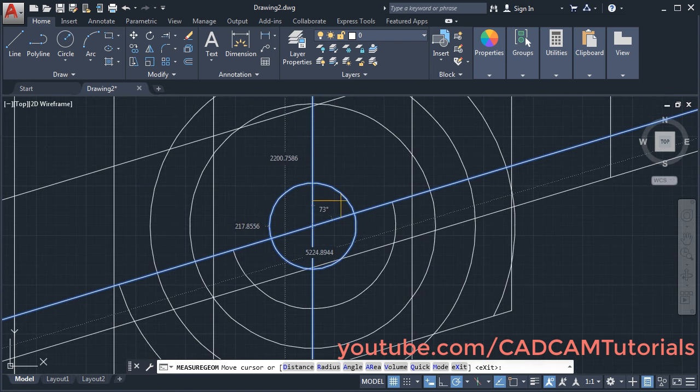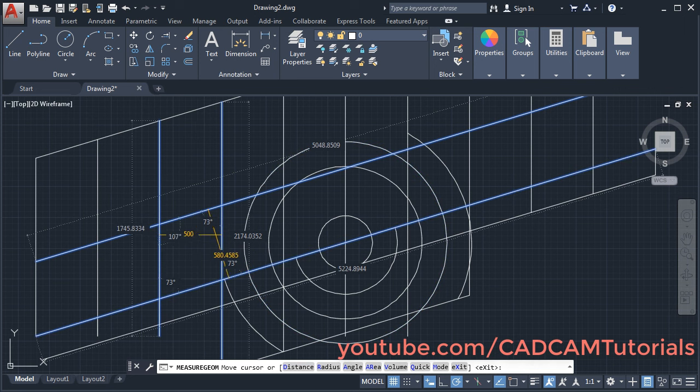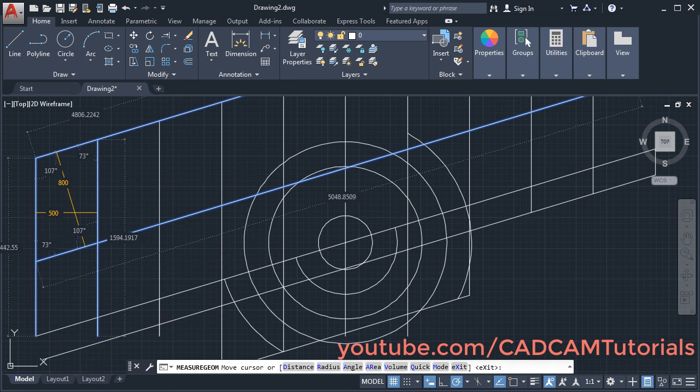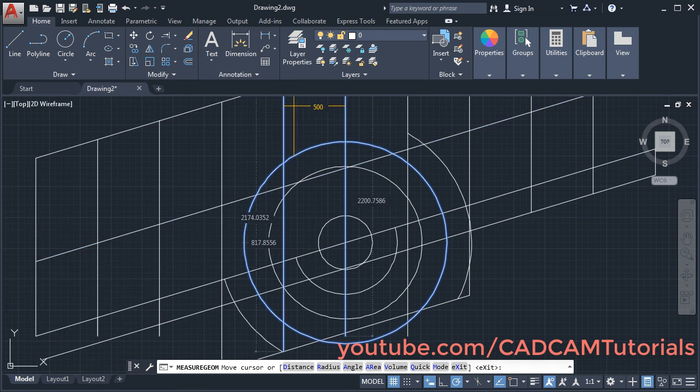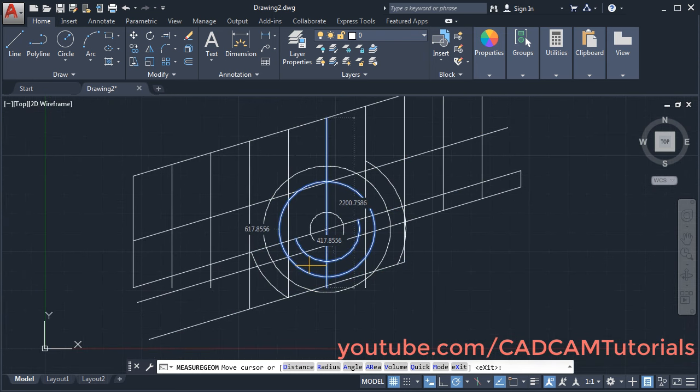So there is no need to click there. You just take it there and hold it for some time. Now it is showing the length of two lines, angle and radius. So this is a quick way to do the measurement, but it is available only in version 2020 and it is not available in old versions. Press escape to come out of the command.